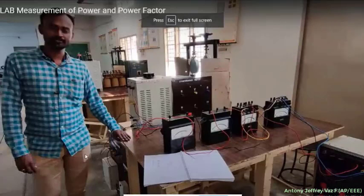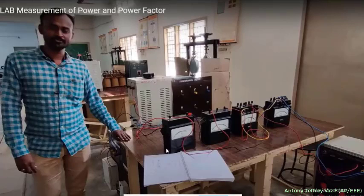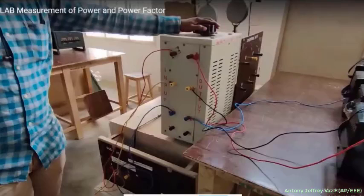This is our lab setup. Here you can see these are the meters which are connected to the load. This one is the voltmeter, this one is the ammeter, and these two are the wattmeters. This one is the auto transformer, and this one is the main board where we connect the input supply. Here you will get the three-phase input, and from it you use the connecting wires R, Y, B.